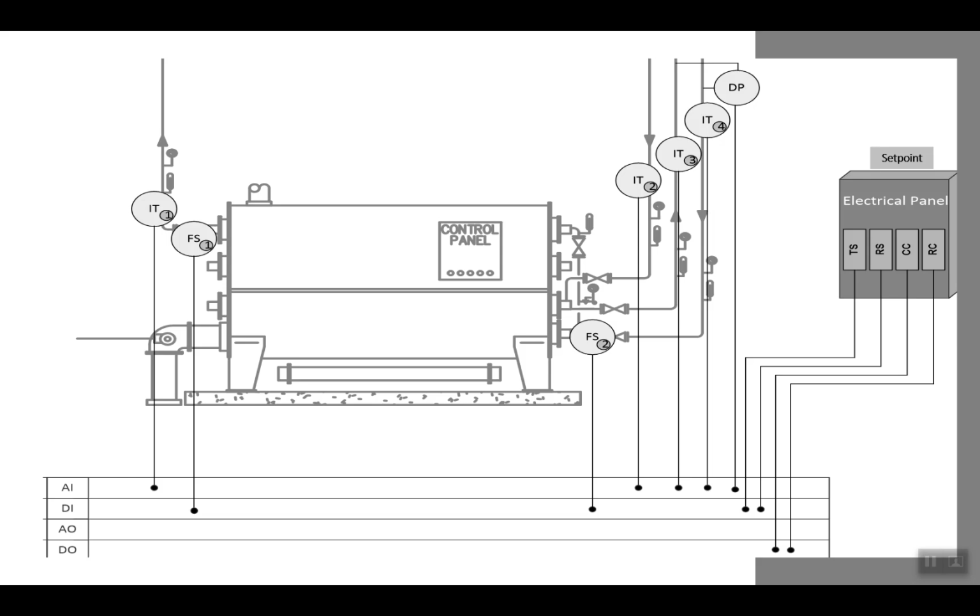So let's start. This is a schematic figure of a simple chiller. You can see we place different sensors and actuators to control and monitor this chiller. Also, we have an electrical panel part, the brain of the chiller, to control and monitor it individually at the place of the chiller. So we start by monitoring the temperature at the input and output of the evaporator.